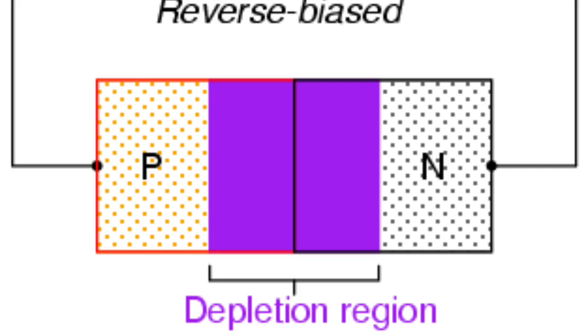Half of the diode is doped as P region and the other half is N region. There are two things between the regions, which are the PN junction and the depletion region. My friends are going to talk about it later. So let's just concentrate on the P region and the N region. The P region will act as the anode, which connects to the first conductive terminal to the voltage source, and the N region will be the cathode that connects to the second conductive terminal. It will change due to the bias process, which are forward bias and reverse bias.